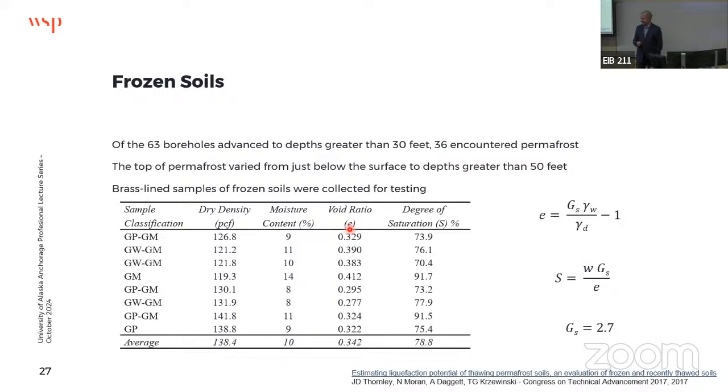They liquefy, and I'll show you how, right? It takes a big earthquake, and a really loose gravel. Now, the next question you can ask is, so what? Because one of the reasons we don't have a really good database about liquefaction of gravels is that we don't know where they happen, because we don't see a lot of settlement due to that liquefaction, like we do in sands and some others.